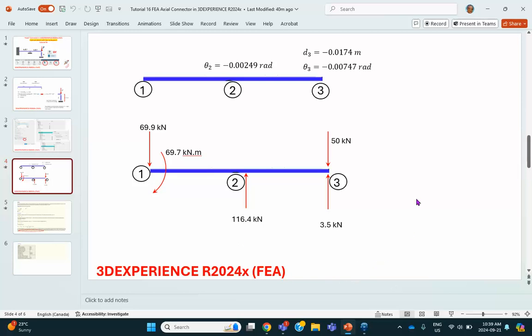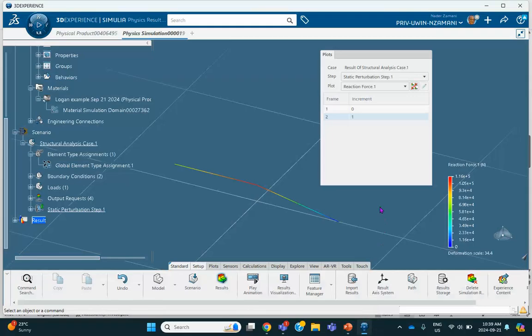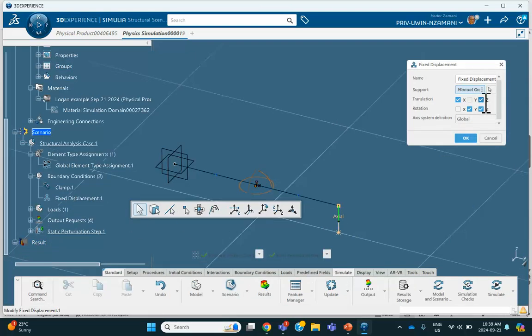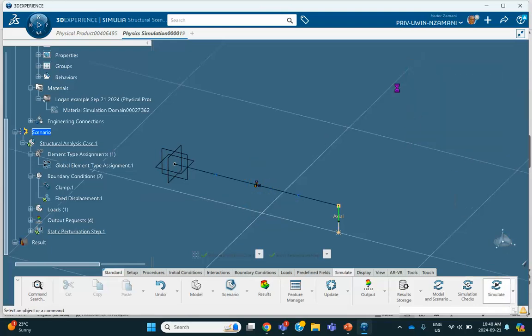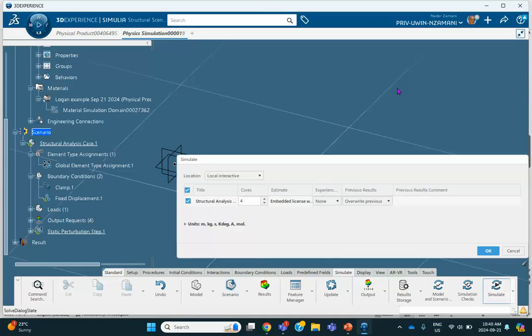Now, let me go back here, and I told you something, remember I created this group there? Let me do it differently. Let me go to this loads boundary condition. This was the roller. Double click on it. Right now, it's on that group. Let me remove this first of all, and instead go and select this point. It took a vertex. And I say, okay. And let's go try to run it. Let's see what happens.